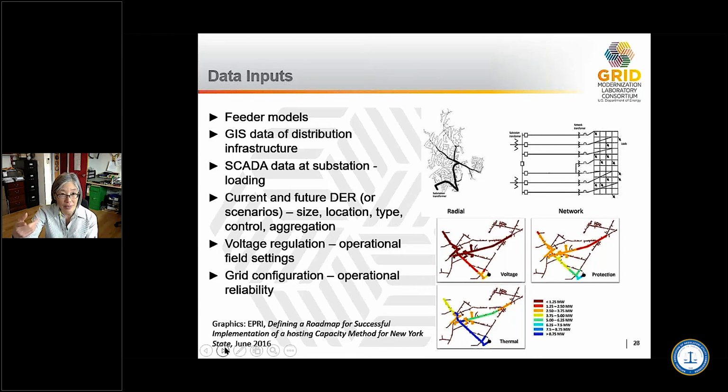National Grid, the utility that I just showed in the last section, has SCADA on 70% of their substations and feeders. They can get their hourly load profile data, their interval data, from that. But for the other 30% of their substations, you have to go in and manually read. They have analog meters and a little plastic indicator, and you kind of reset it.